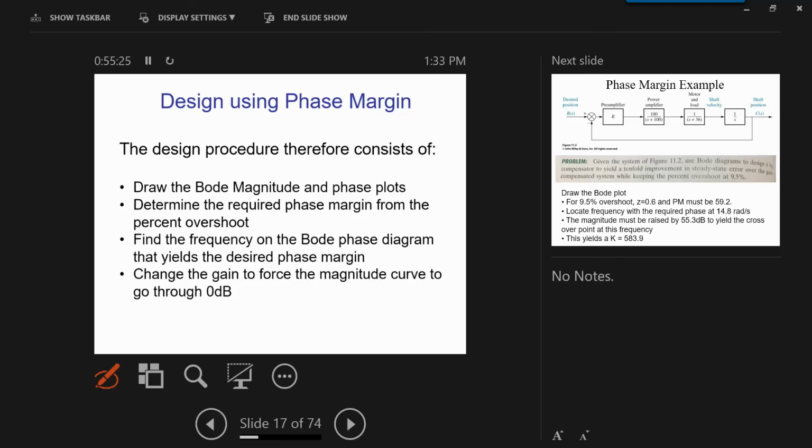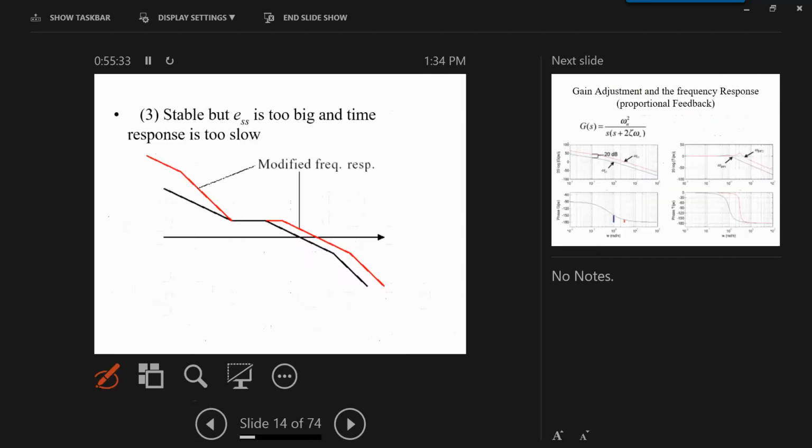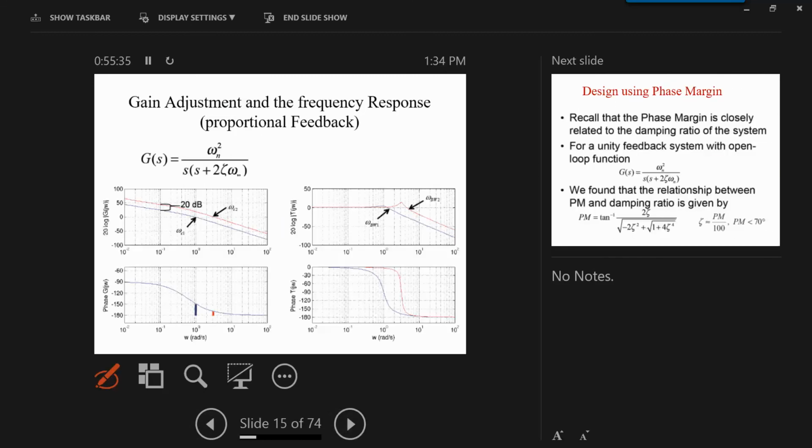Yes. So you said you wanted to increase the phase margin, right? Aren't you automatically increasing the damping? Well, yes, we are increasing the damping, and here, this is my system. This is the open loop system, the blue system. Now this is my phase margin. Really, I want a 60-degree phase margin, and it is here.